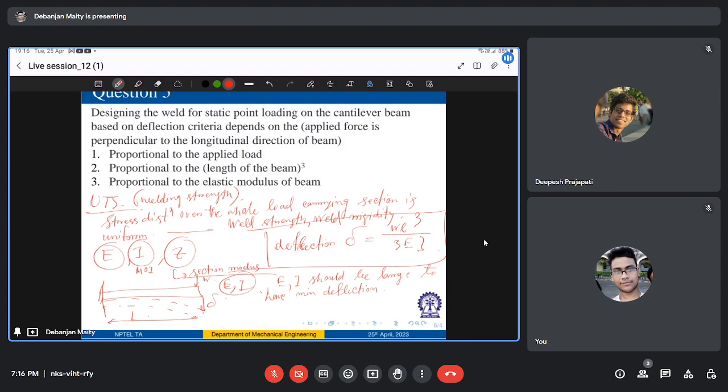So basically in terms of designing, we'll have this failing stress or factor of safety, right? You'll have this failing stress or factor of safety. So this way you have the definition of allowable stress or working stress, which is what you set for the design of the weld specimen for some satisfactory long run, right?